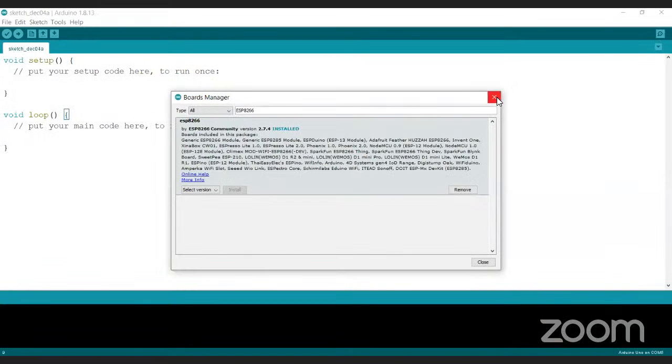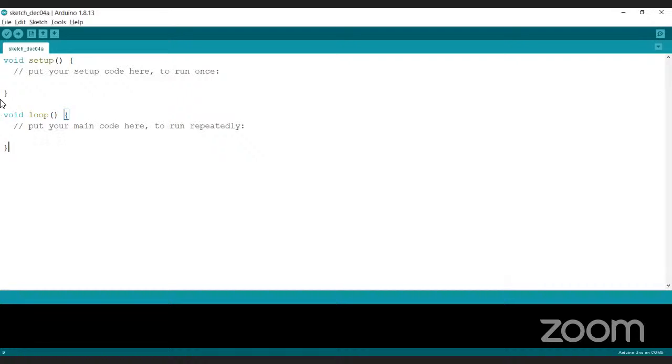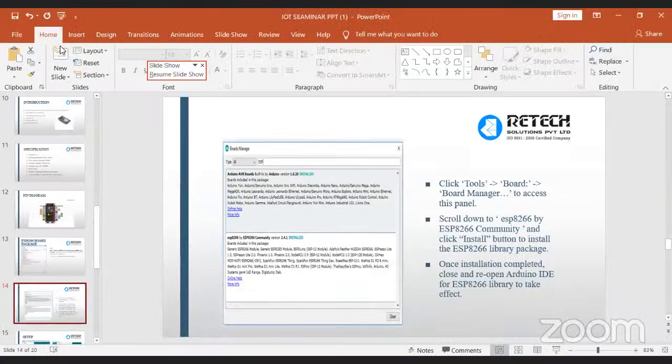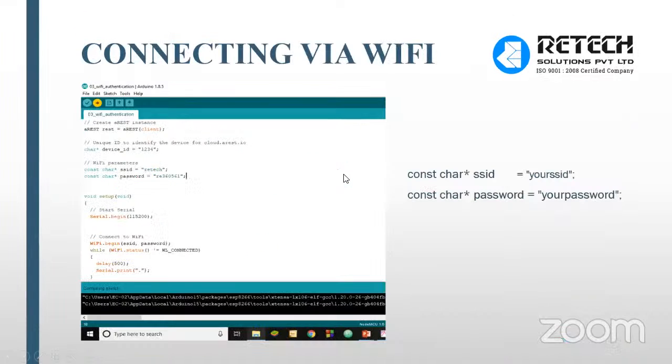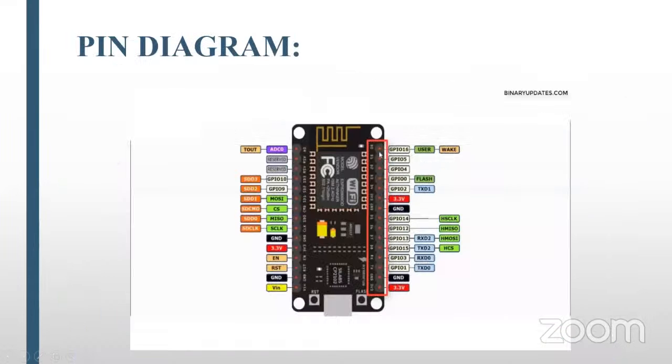This is the Arduino microcontroller, the Arduino IDE. Like the ESP8266 microcontroller, it has only one analog to digital converter. That pin is called ADC0, like A0. Via that pin we read the sensor data.